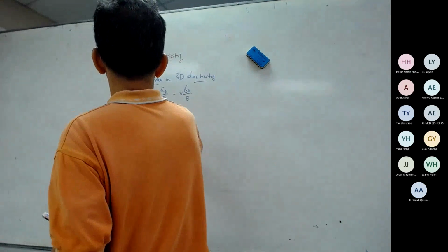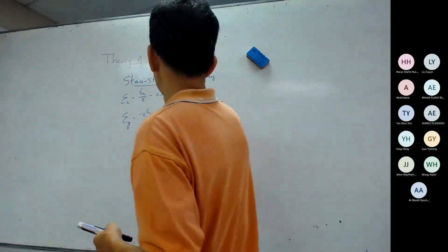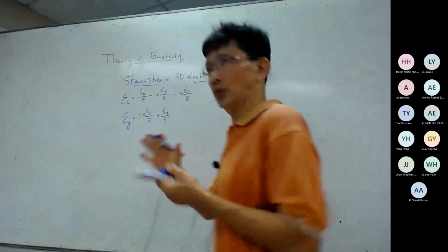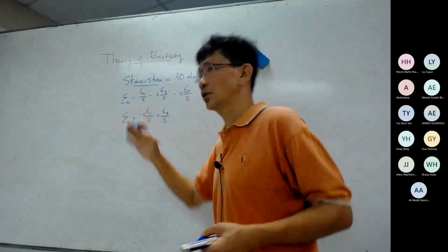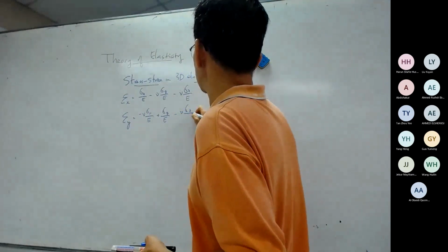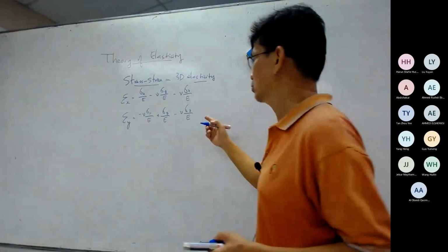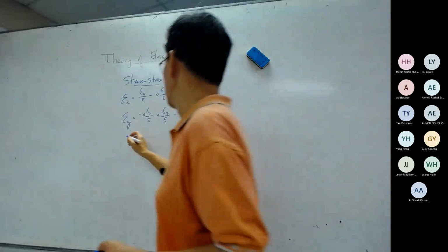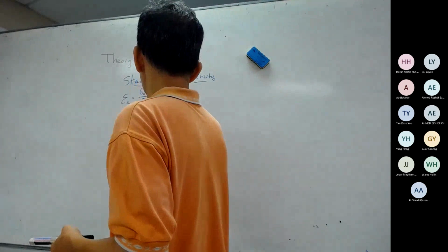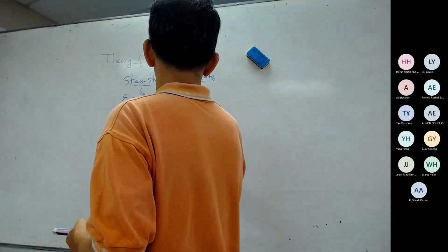So positive stress in x direction will cause negative strain in y direction. Then you have a direct one, because direct stress, positive stress in y, is going to cause positive strain. And then positive stress in z direction is going to cause negative strain in y direction. This is the so-called Poisson ratio effect. Then the same thing, just I write it down here. Plus this. Okay.